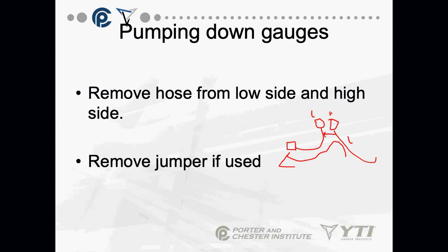Don't ask me how much a de minimis release is, because there's no definition anywhere on it. It's a release of refrigerant that is totally within EPA guidelines, but again, you can't avoid it. So legally, you're not allowed to release refrigerant, but de minimis releases are acceptable according to the law.